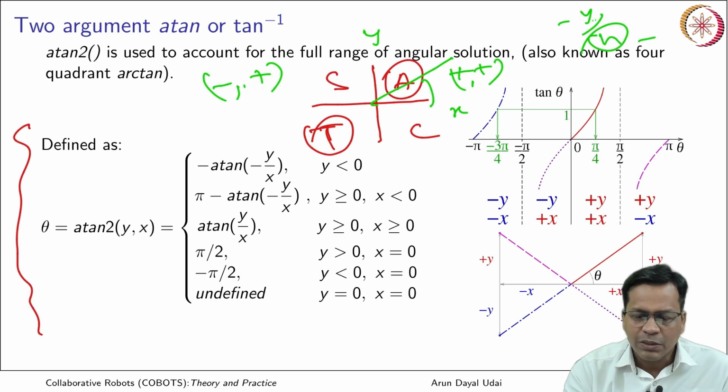But in case of this, you can clearly understand if the robot arm is in positive quadrant or in the second quadrant, third quadrant or fourth quadrant. So depending on them, you can clearly define your theta using programming also. So these are the conditions that you can put depending on positive of x, theta lies here.